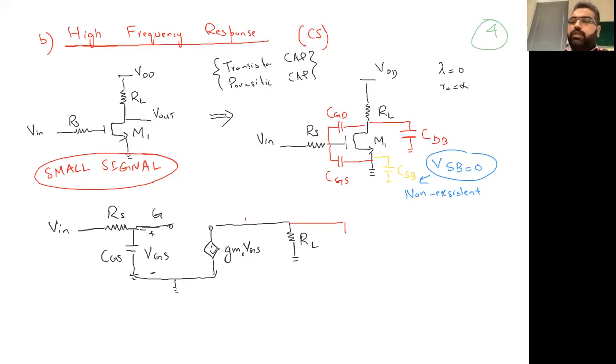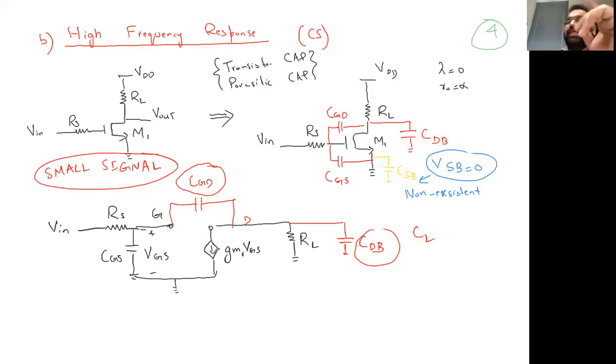So this is a drain for us. So there will be one capacitance CDB, and one capacitance CGS हो गई है, and one capacitance between the gate and the drain, CGD. ठीक. So now everything is clear. That CDB will be load capacitance. CGS input side पे आ रही है. But the thing is that just CGD है, that is in the middle between two nodes, gate and drain.